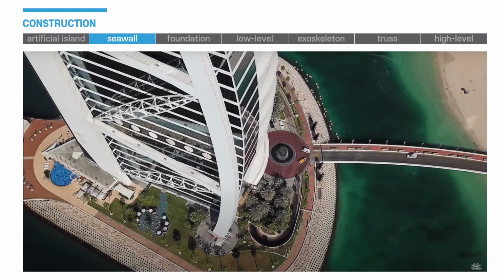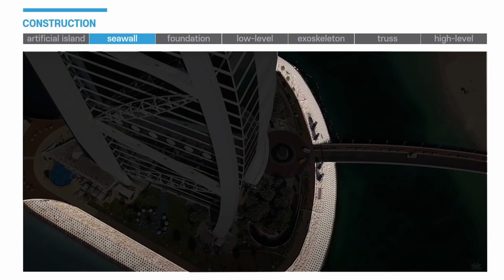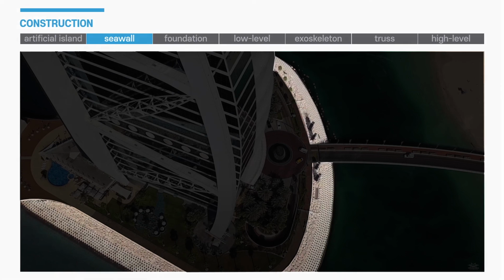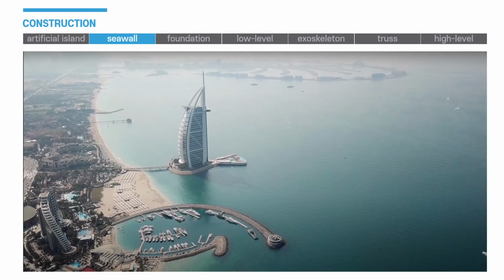Energy reduction wasn't the only reason they chose shed units. The exterior of Burj Al Arab also had to be perfect. Randomly interlocked armor units couldn't fulfill this. Shed units, which are placed uniformly, was therefore chosen. The seawall composed of these shed units could maintain the island's height to only 7.5 meters above sea level and enable the building to resemble a floating yacht.